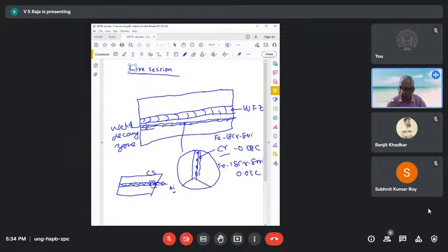One of the problems that happens in the case of weldment is, once the groove is formed, when there's a flowing, there's a turbulent flow, and so more corrosion takes place. It's also possible. And I don't know the velocity of this thing. What is the linear velocity? If the linear velocity is larger, then of course there is erosion corrosion.